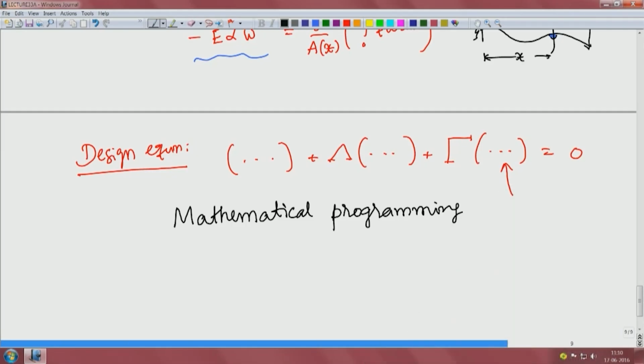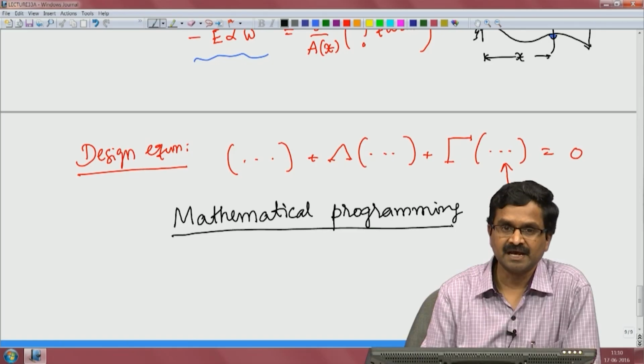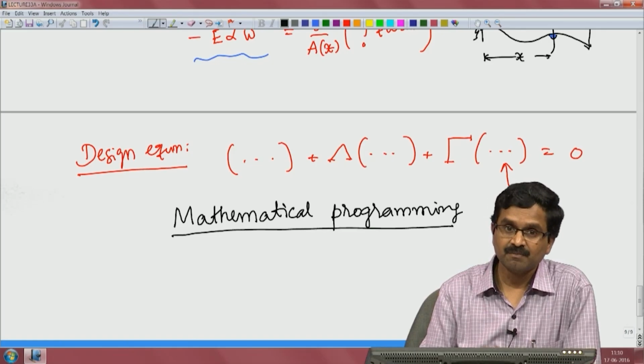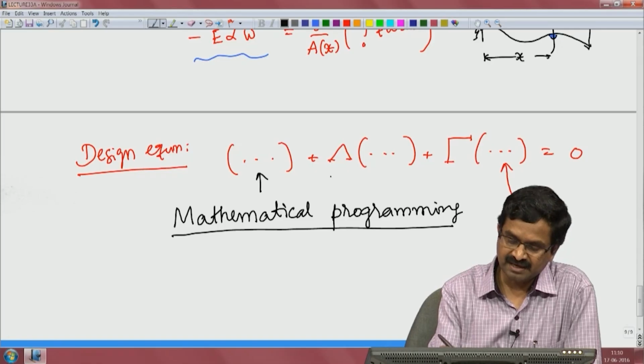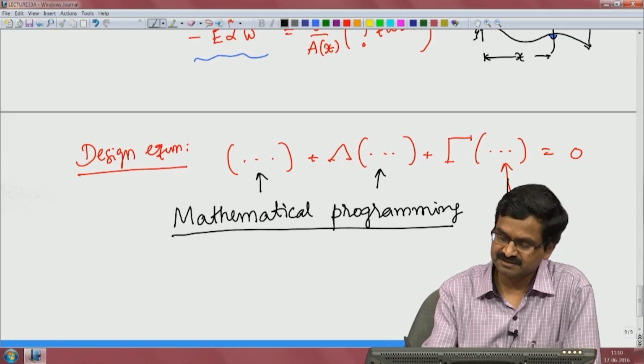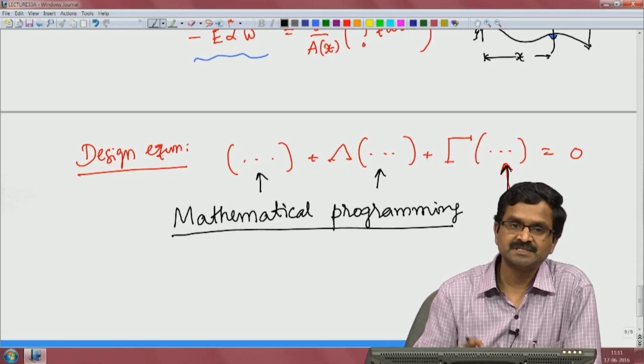The MATLAB toolbox has the fmincon constrained minimization routine, which solves using sequential quadratic programming and trust region methods, and there are many more. Any of those mathematical programming techniques or constrained minimization algorithms can be used to solve, because now you are able to supply the analytical gradients. That is the beauty of this analytical procedure.